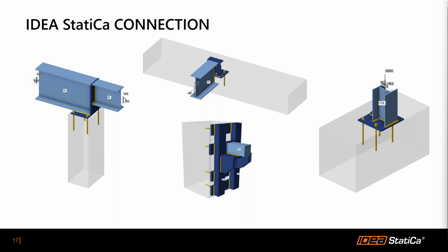Let's get to it. Thank you so much for the introduction and answering the question why. I will be showing how, because I want to talk about the complete workflow of the anchoring solution Idea Statica provides. In some cases, it is tough to solve the anchoring tasks even with Idea Statica Connection. And those cases are, as you have said, close to the edge anchoring to a concrete block, or multiple groups of anchors close to each other.